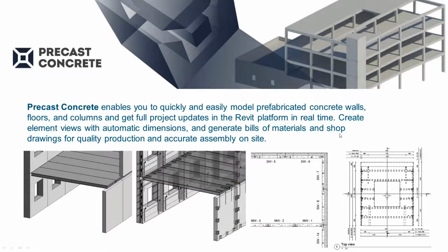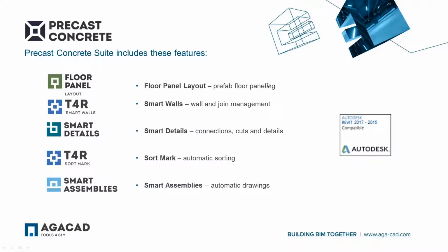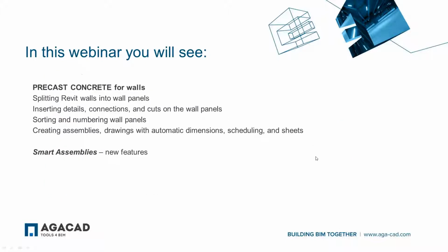I think I will just go to the live demo as quickly as possible. Inside Precast Concrete, we have 5 tools: floor panel layout, smart walls, smart details, sort mark, and smart assembly. You see the description here, and you will see a live demo of them. We will not touch floor panel today because it's just for slab modeling.